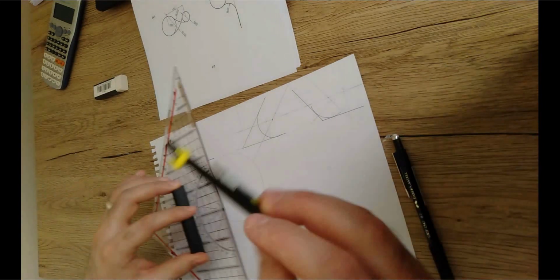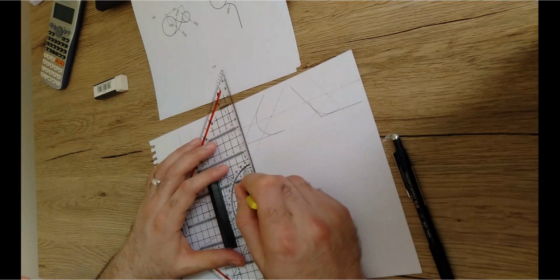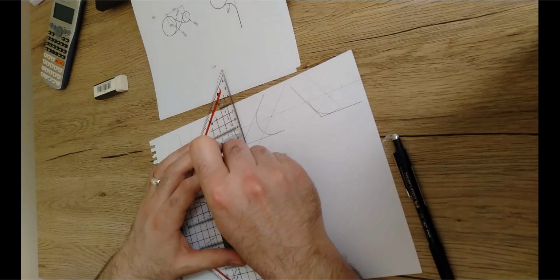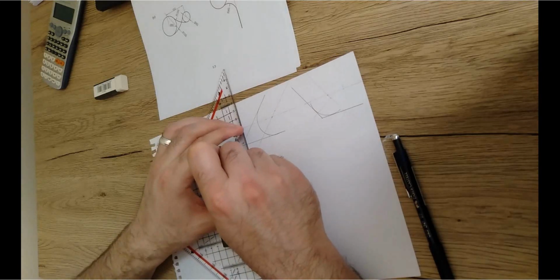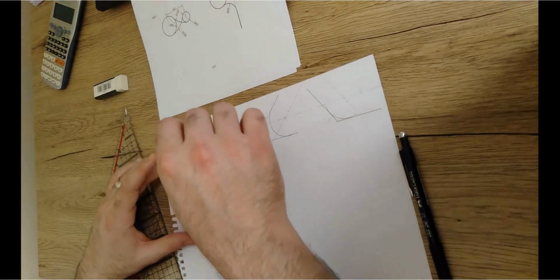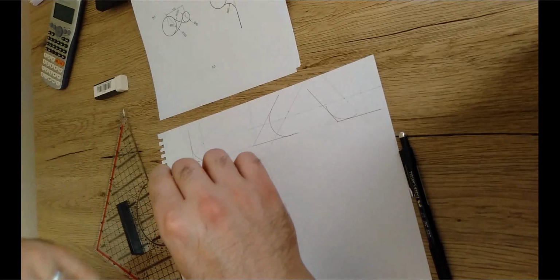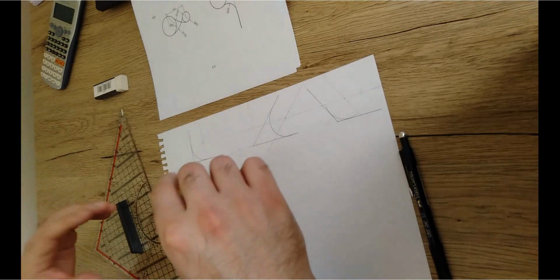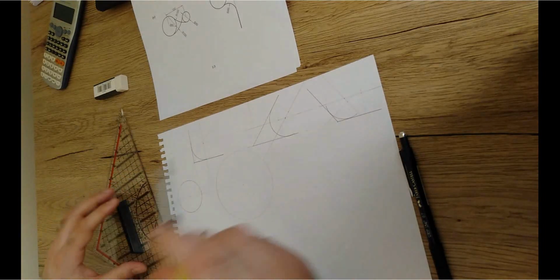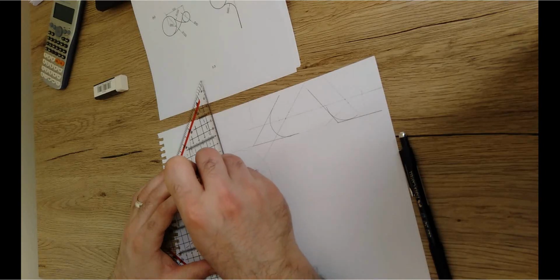So first of all, open the canvas with the 80 millimeter. From this point, I'm gonna open with the 80 millimeter this way. Then I'm gonna fix in this point and draw a big arc. Doesn't matter that it intersects with the other joint, because all of these are just locus lines that we're using to assist us to locate the center points of the curves, but no problem. Then from the other small circle, I'm gonna open with the 60. So it's gonna be 60 in this way.